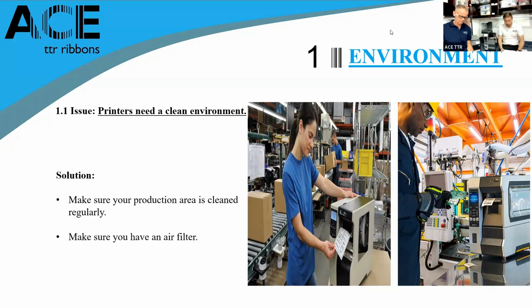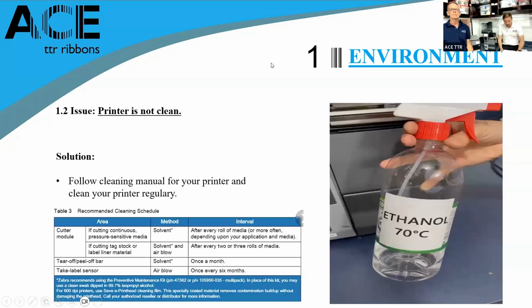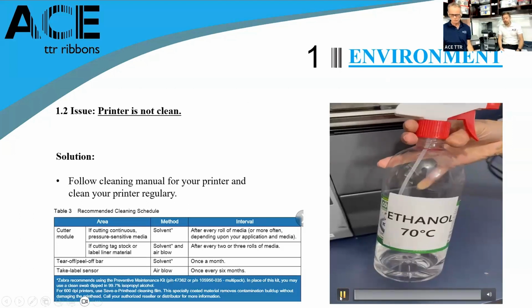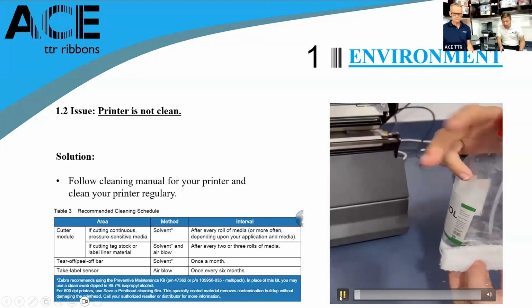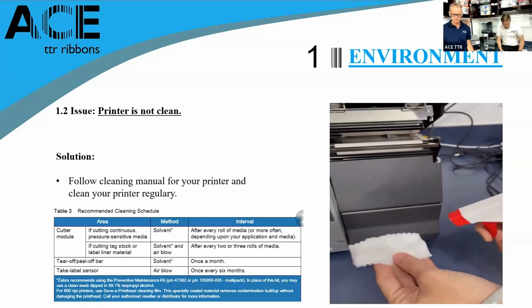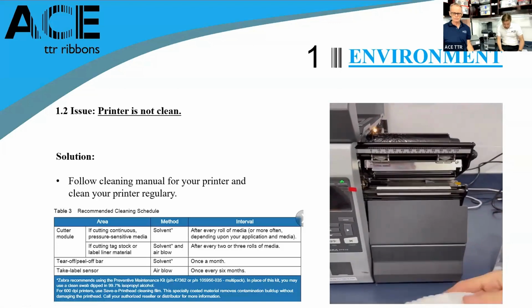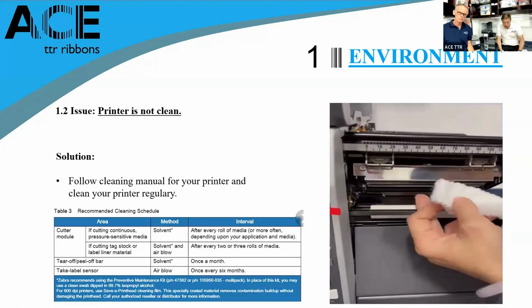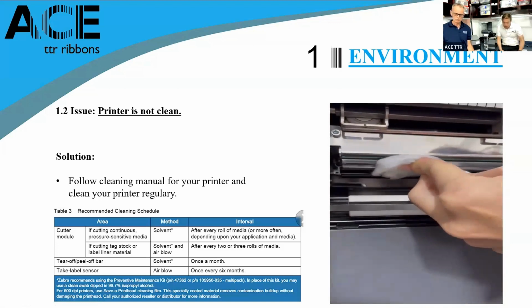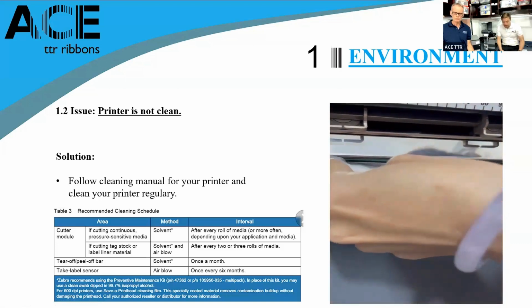It's very, very important to keep your printers clean. Dust on the printer will reduce the printing quality, and also it will reduce the lifespan of many important parts like printheads. And then you can see here on the video how Maria from our development center cleans her printheads. So it can give you some idea. She takes soft microfiber material, she applies 70% ethanol alcohol on it, and she carefully cleans the printheads.